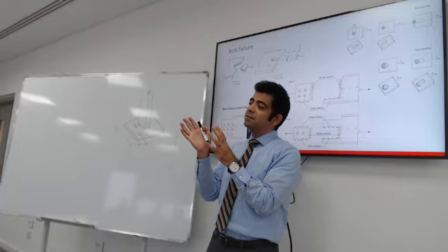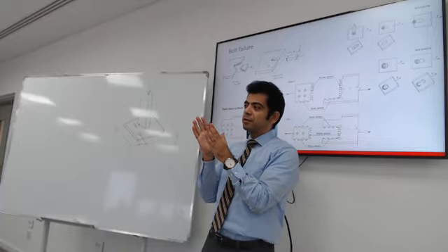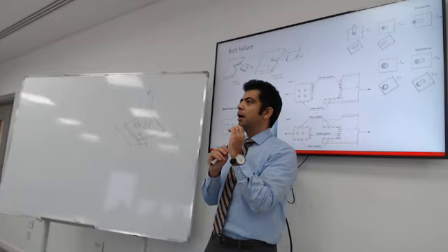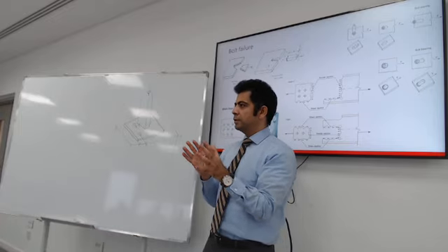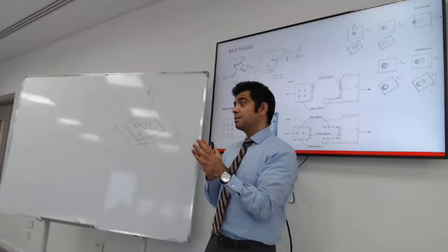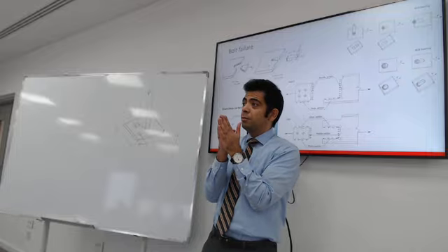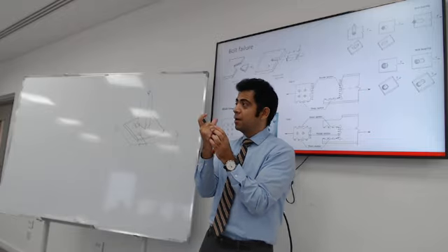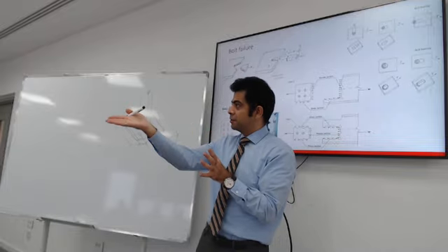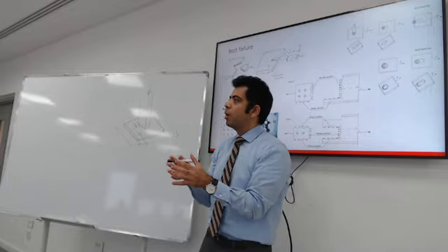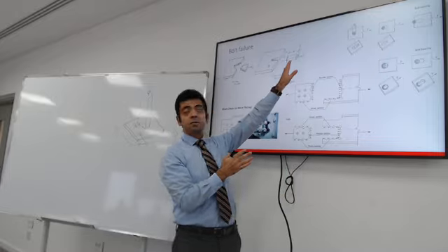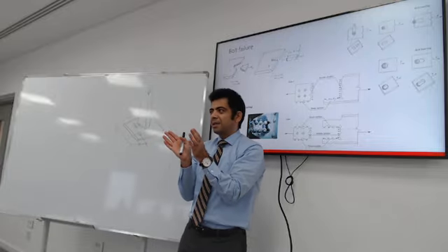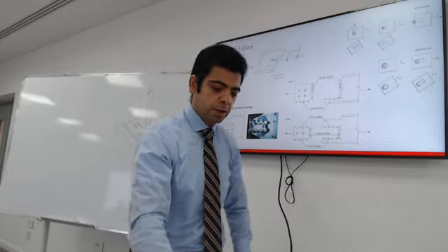Any thoughts about this answer? It seems like you wanted to say the assumed will result in a bigger capacity. Did you mean it's more conservative? Yes. It is more conservative because it's assuming that the failure shape will happen on a smaller surface. But in reality, the failure surface is bigger. That's why it's safe to assume that this is the failure shape, because in reality, we will have a slightly bigger failure shape. All right.